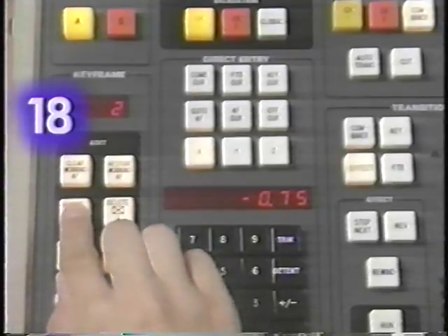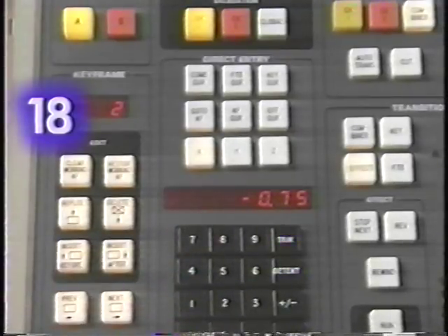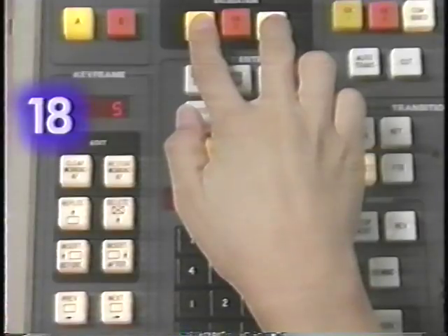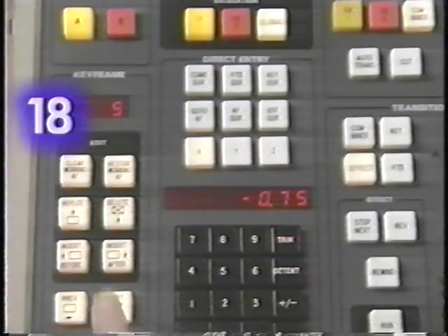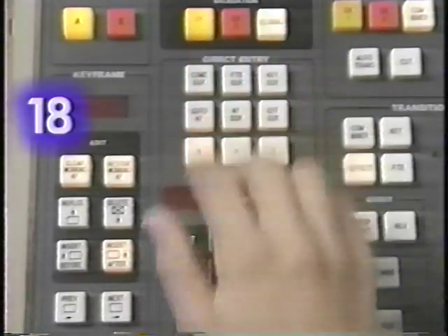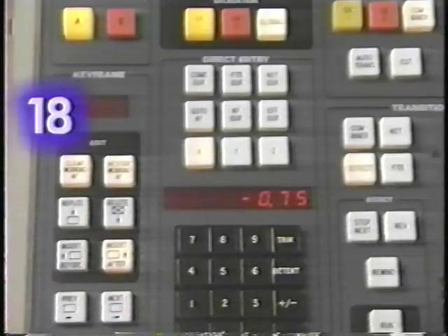If you park on a given channel's keyframe and modify it, all editing functions are active. If 2 channels both have keyframes at exactly the same point in time, you can park at that point, delegate to both channels, and modify them both at the same time. Again, all editing functions are active. If there are no keyframes in either channel at a given point, only Insert After is active, as there are no existing keyframes to modify.